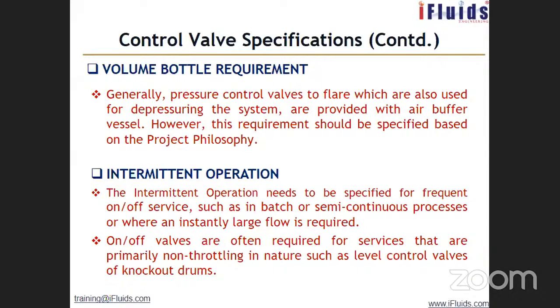You can see your toilet flush, you have seen it, isn't it? Once you flush, the water gushes out and cleans the toilet, then the water level is low. If you open the toilet flush tank, you would see a ball float sitting on the water level. The ball float is connected to the inlet valve in the inlet water line.